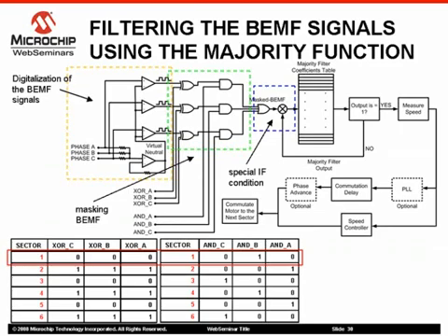This filter is implemented with an array composed of 64 values and a special logic test condition that is used to modify the pointer to the next data array. This logic test condition also identifies both the falling and rising edges of the active masked back EMF signals. Both edges are represented as a true to false event at the output of the logical test condition. The output of this condition is also used as an input to the majority detection filter.